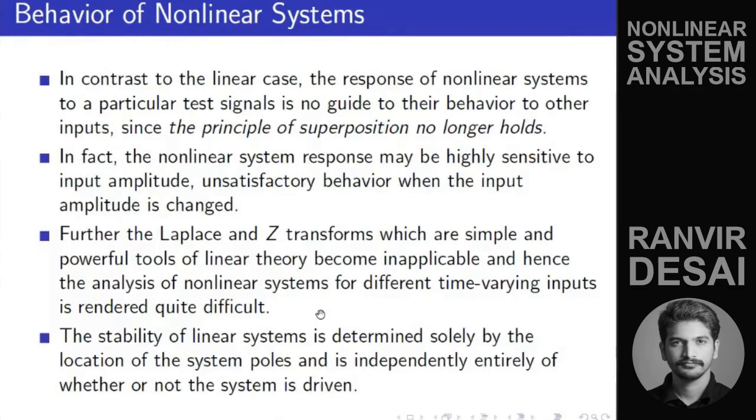See, convolution in the time domain becomes multiplication in the frequency domain. So you take the Laplace transform, take the multiplication, and then take the inverse Laplace transform. You have found the convolution. It is easier to do some things in the frequency domain. Okay, so those are some tools that make an engineer's life easy, but not in case of nonlinear systems.